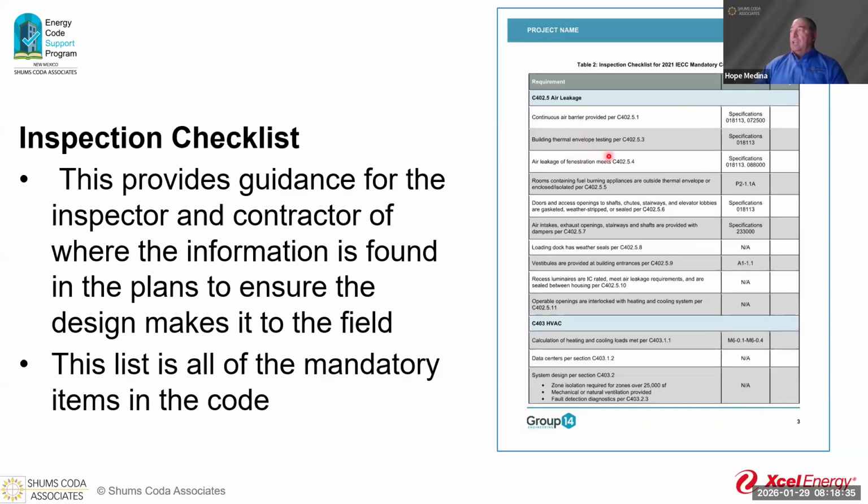You can also see on here that we have stuff that's not being addressed. So right here, our loading dock, not applicable. Don't have one in the building. If you show up as an inspector and you find a loading dock door, you may want to question that. See if we have the right set of plans, right set of documents for the checklist. And if not, then we need to add that to the plans.